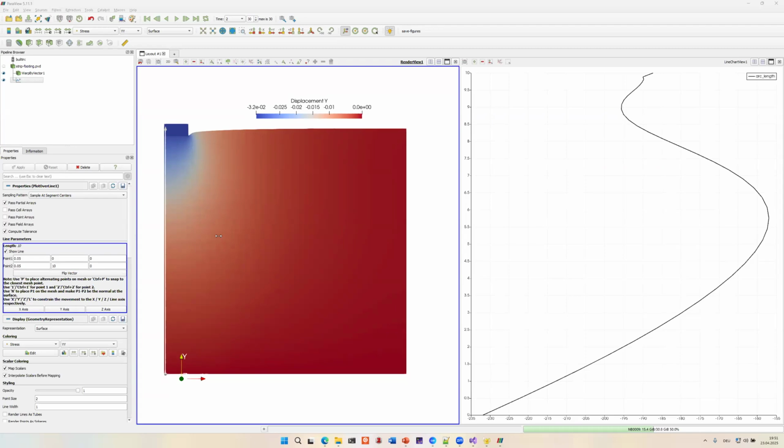So such an earthquake simulation of 20 seconds length, depending on the distance of the epicenter, the longest took about 2 to 3 days on a standard workstation. So it was okay. In terms of 3D, we have done a lot in terms of pile raft foundations and also monopiles, right? And foundations for wind turbines. And there we usually have quite a few 10,000s of 3D elements in these cases.